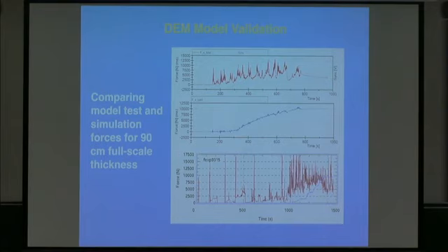The physical model has these distinct ice push events where the force starts out low, rises, and then falls. These are correlated to individual buckling events in the ice sheet approaching the structure. The numerical model is really, really noisy. You don't see these discrete push events. You see a long period initially where it's just filling in the area in front of the structure. When it finally gets to be riding up onto the structure, you get a higher force, but you still don't see that qualitative rise and fall.